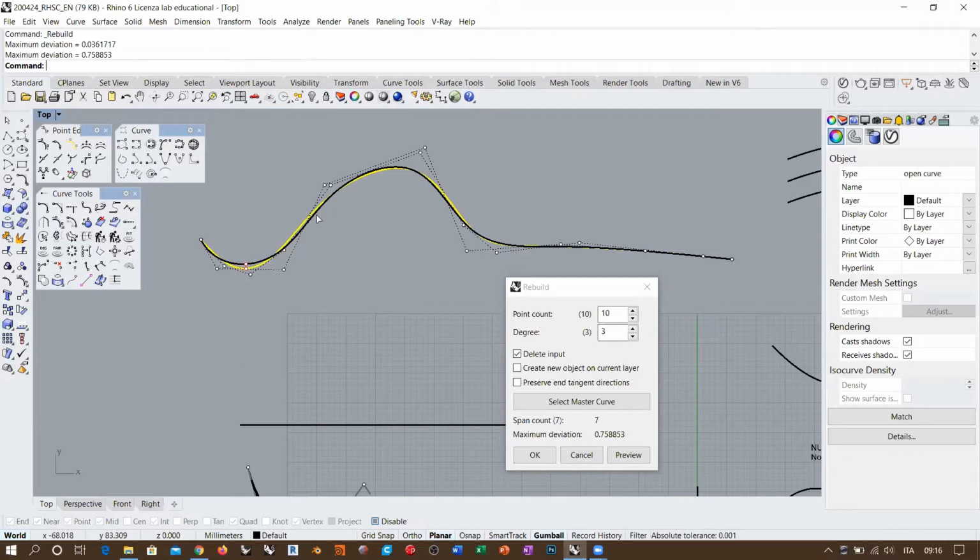But if this is the path of a highway, and we are drawing in kilometers, for example, these are 750 meters of maximum deviation, which basically should mean also that there is some landlord that is going to be upset because we are taking away his land. So it depends on what we are drawing, basically. So this is neither good nor bad. Okay, so you must see if this affects your design in a relevant way or not.